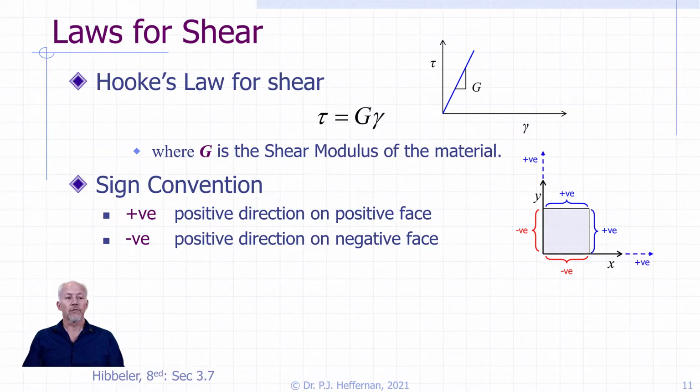And we put those together with the direction that they're pointing. I'm showing the positive directions there and the negative directions here. Between all of that, we're able to define for a given shear stress whether it is a positive shear stress or a negative shear stress. This is something that you probably want to practice a little bit and pay very close attention to when you're going through your problems, because it is an area of confusion and common mistakes when starting out doing some of these problems.